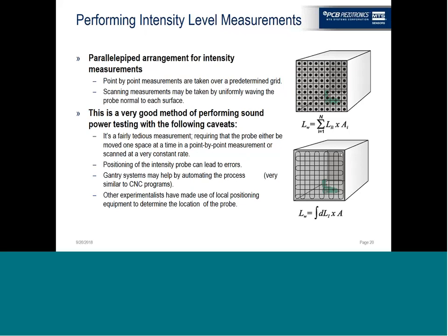Sound intensity, it's a very good and a very accurate measurement. There's a couple caveats. It's a pretty tedious measurement, requiring that the probe is moved fairly repeatably. Positioning of the probe can be kind of a pain. Again, if you want to really set it up well, gantry systems will help automate the process. And then also local positioning systems are very helpful in doing sound intensity measurements.